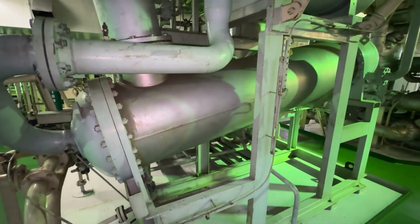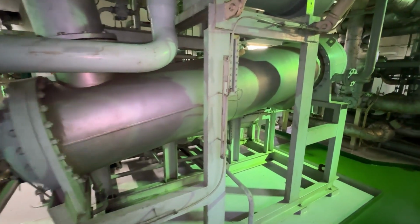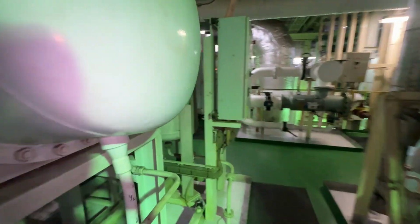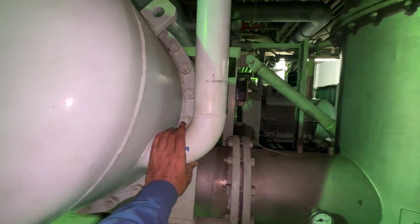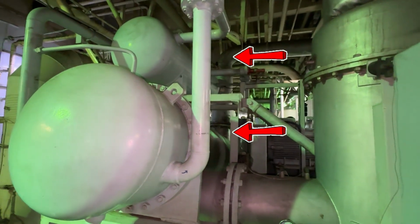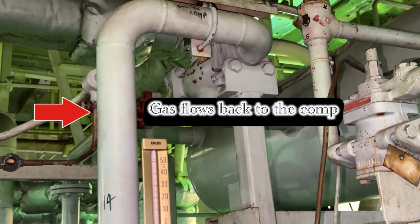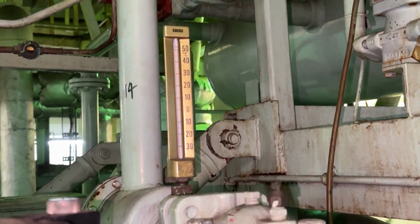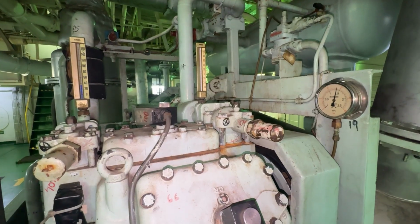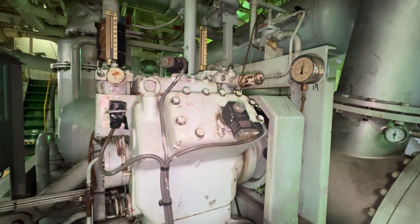And this is how the evaporator looks. In the evaporator, heat exchange takes place and the liquid becomes gas, and this R22 gas will flow back to the separator through this pipe, and this gas settles at the top of the separator, and this gas will flow back to the compressor, and this cycle repeats again and again. And this is how R22 flows in the chiller plant.